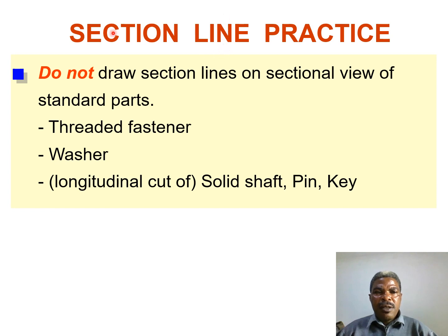For the case of section line practice, do not draw section lines on the section view of standard parts. We have already expressed this: threaded fasteners, washers, longitudinal cuts, or solid shafts, pins, and keys are not included in sectioning.